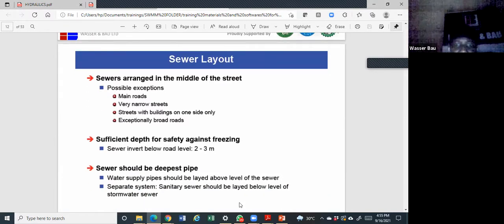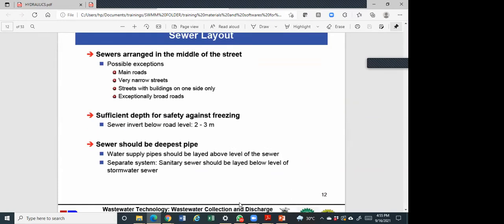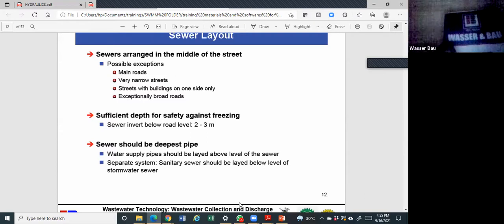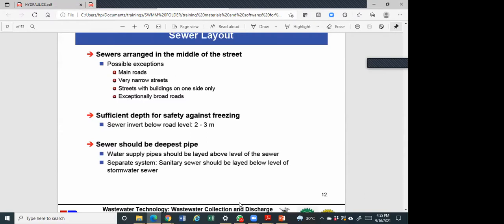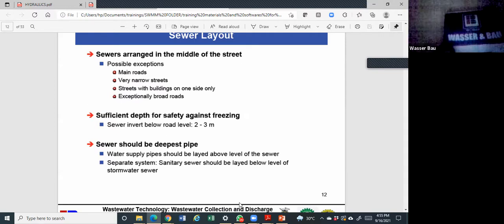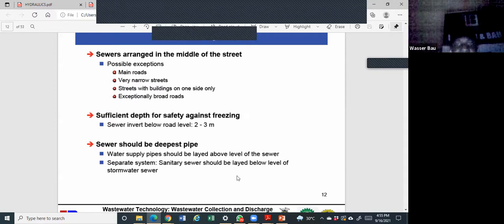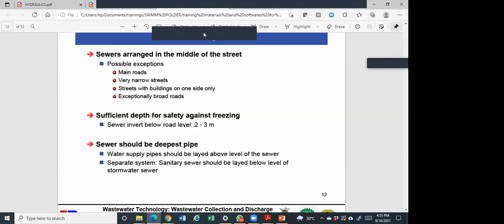Sorry. Go ahead, sir. You mentioned when you introduce a manhole: when change of size of pipe and slope. Yes. Direction. Change of size. Direction. And maintenance. Okay. What of maximum length allowable that you can lay? 60 to 120. Between 60 and 120. It's in a manual. You will see it very soon. There is a range, sir.